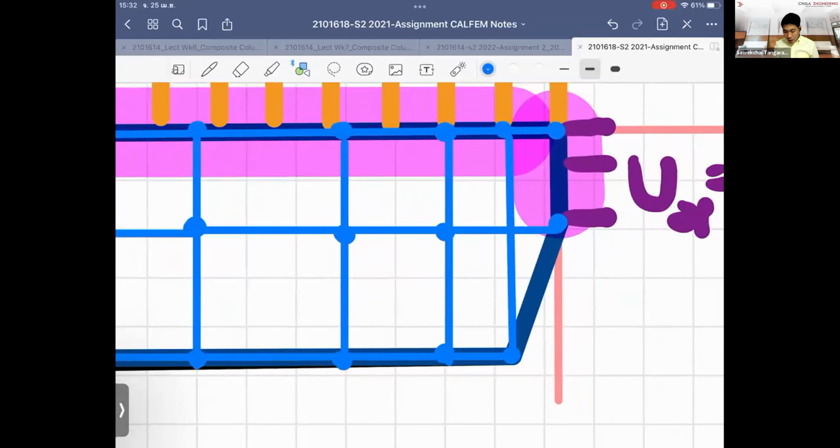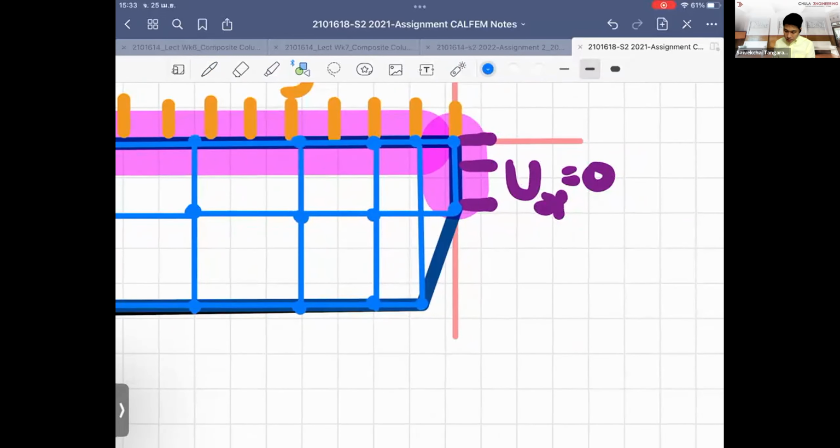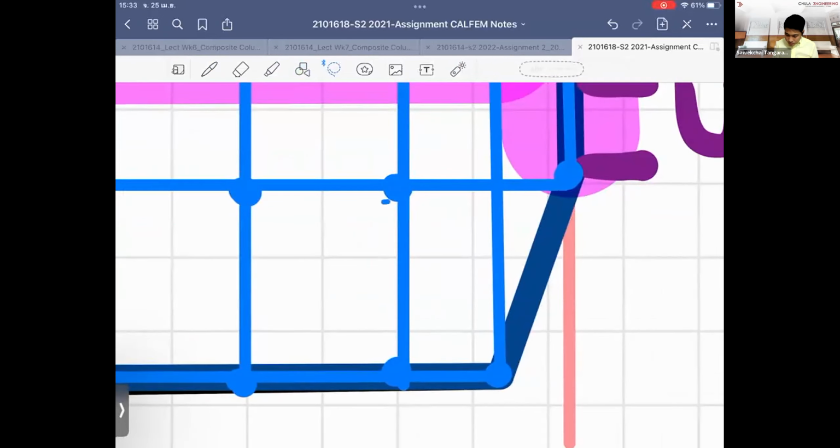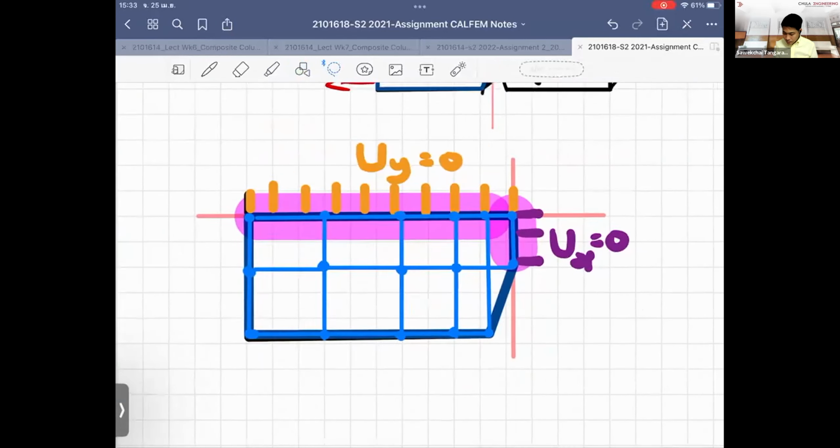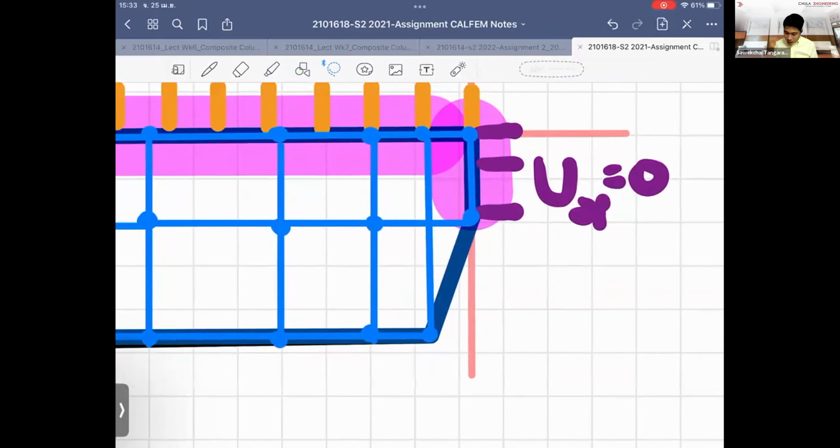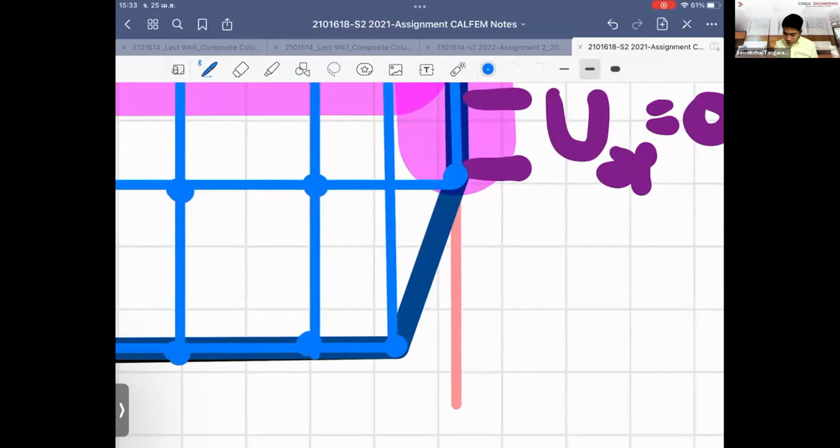If we're doing this, there is a problem. Can you identify the problem here? We don't allocate a node here. The problem is that when we have two other finite elements, if we don't allocate a node at this point, the element that you have... Of course, sorry, you can try the 4 node element.